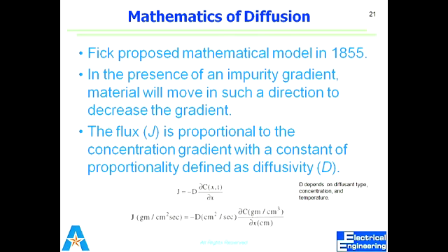So initially, let's suppose you started with this: it was only on the surface. This was only the thickness that had that dopant. It was only on the surface. After some time, at high temperature, it moved up to X2. But the surface concentration, you can see, has decreased because now you don't have the source. Whatever you had, that is constant. After some more time,